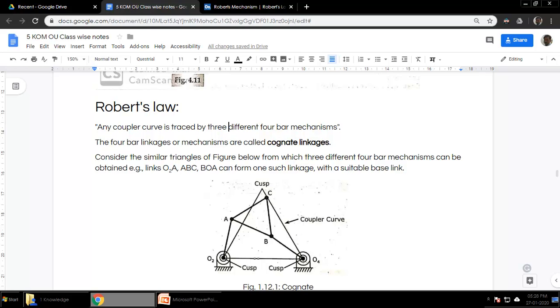In this particular case, we have taken an equilateral triangle, and from the midpoints of these two links we have got this upper coupler. The bottom links become one the crank and the other a rocker, and we get rockers in both mechanisms, because this four-bar mechanism doesn't satisfy Grashof's law, and hence comes under the type 2 four-bar linkage.